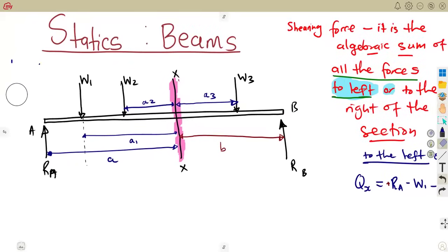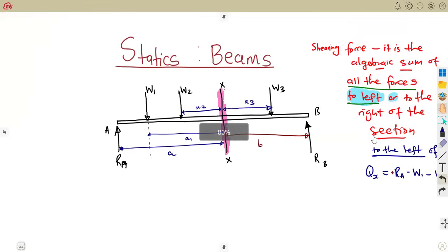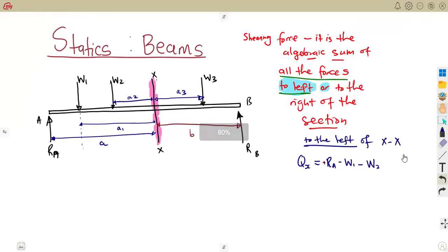The shear force, as you had when you were drawing the shear force diagram in your N3, don't mind, guys. They just want you to say, okay, maybe you want to calculate the shearing force at a certain point. That's why we've got these formulas, so that it enables you to calculate the shearing force at any point. But guys, as you had those calculations without a formula, you're just subtracting values. When it is going up, you add. When going down, you subtract. That part is not going to change from your N3.